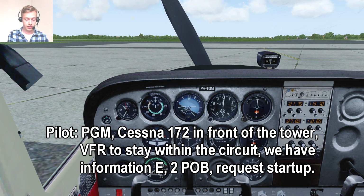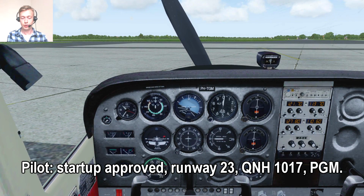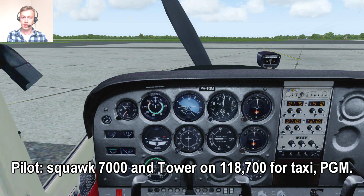So let's see how that goes. Papa Golf Mike is a Cessna 172 in front of the tower, VFR to stay within the circuit. We have information echo, 2 POB, request startup. Papa Golf Mike, startup approved, information echo correct, runway 23, QNH 1017. Startup approved, runway 23, QNH 1017, Papa Golf Mike. Papa Golf Mike correct, squawk 7000 for taxi, contact tower on 118.7. Bye bye. Squawk 7000 and tower on 118.7 for taxi, Papa Golf Mike.